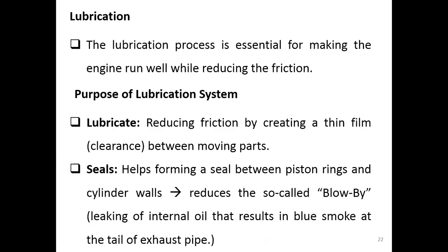And if our piston speed is greater than 15 meters per second, our friction force becomes dangerous. So we have to analyze the force in the piston in order to avoid any dangers that will happen to our engine under high speed.